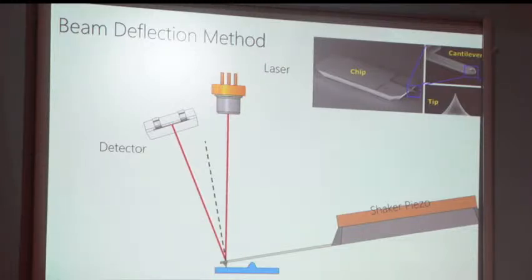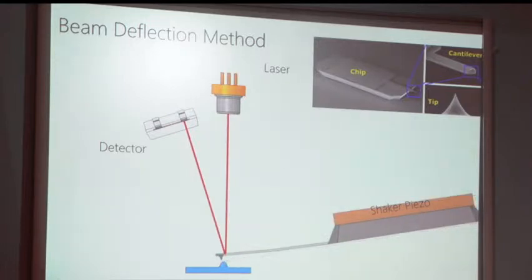So what happens now? If the cantilever moves to another position on the surface, suppose there is a bump on the substrate, what happens? The cantilever has to bend. And at the same time, you saw the laser which was at the center of the detector also got moved. Now, the job of the AFM controller was to bring back this laser onto the center of the cantilever.